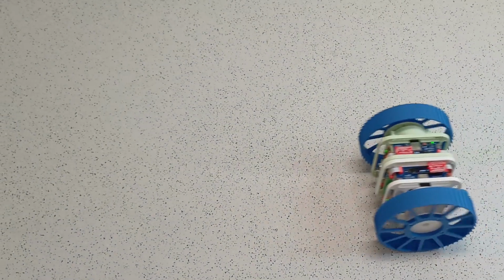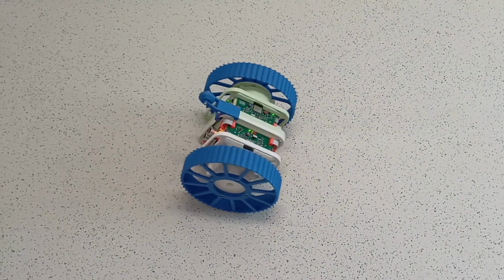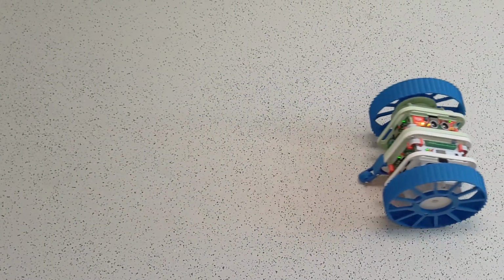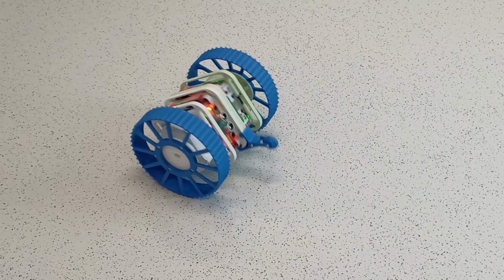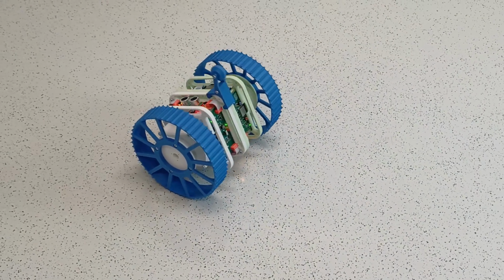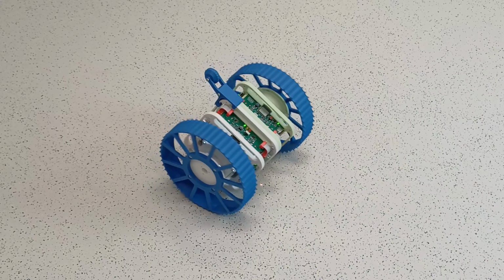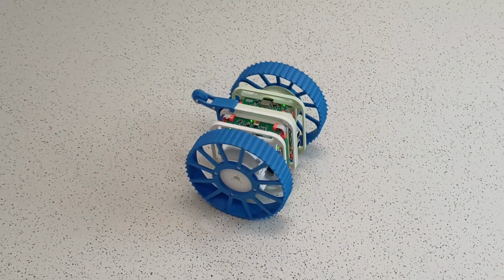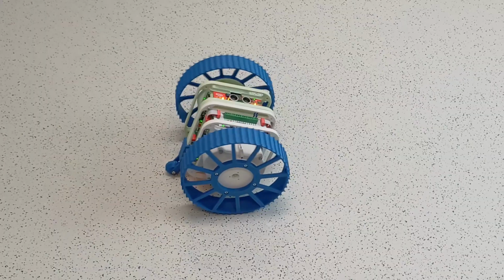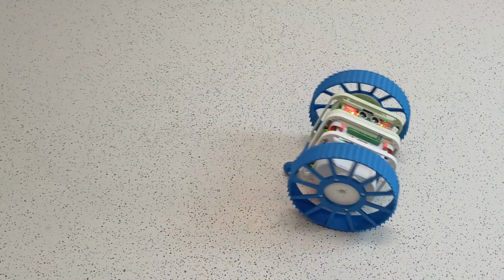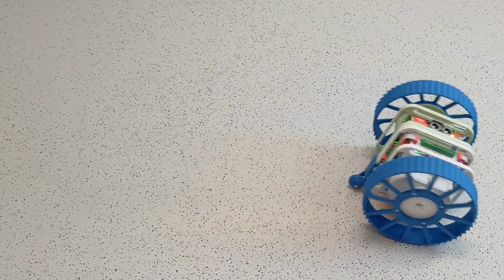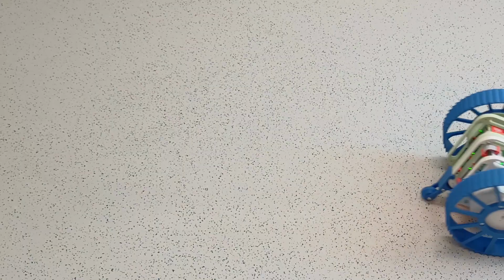Now that we have two servo motors, we can connect them so that the wheels share the same axis of rotation. The robot would also work if the output shaft were at an angle. Just worse, because wheels would have to slip for the robot to move straight. Because the center of mass of the servo motor is close to the axis of rotation, our robots need an additional support so that the body doesn't rotate while it tries to move forward. As the support is only on the back side, the robot shouldn't decelerate too fast, otherwise it will roll over.